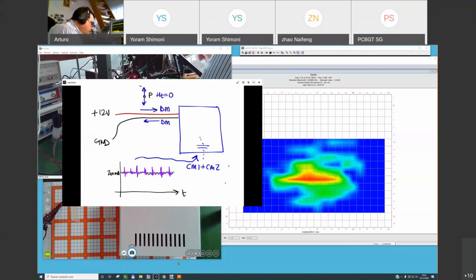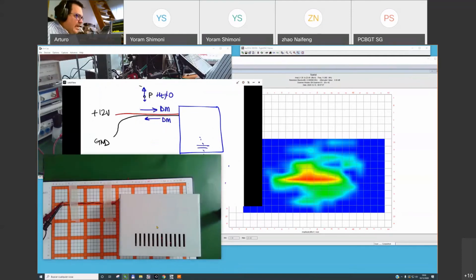If you move this cable far away from the first one, what happens is that the second field will be smaller, and then the magnetic field in the victim will not be cancelled. But usually, many people do this naturally. You can see this in my picture. I have a red and a black wire that are one close to the other.